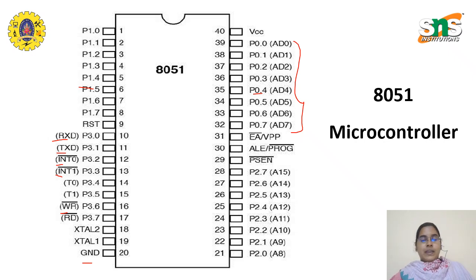Compared to that, the 8086 has the unique feature of the pipelining technique, which helps in fetching and decoding operations, a better way to avoid the delay of fetching instructions. And compared to the 8086, the 8051 has the advantage of inbuilt memory and inbuilt peripherals. So each microprocessor or controller has advantages and uniqueness. Depending upon the application, we can choose the controller or microprocessor.